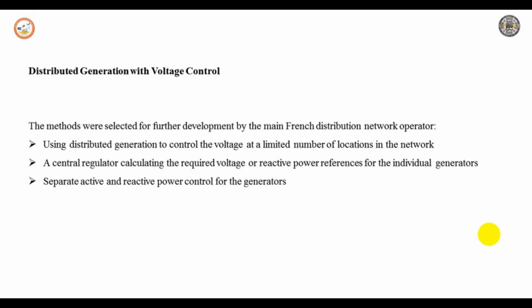Most existing wind turbines, even when they have the ability of reactive power control, are disconnected when the wind speed drops below the cut-in speed. As a result, reactive power capability is not available during 20 to 40% of the time. A decision towards reactive power support which is available continuously should be made early in the discussion between the network operators and the owners of wind turbines.